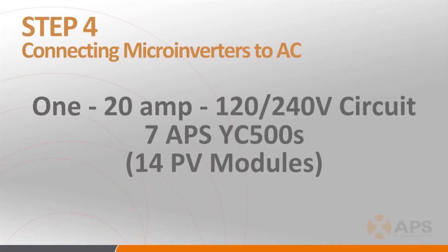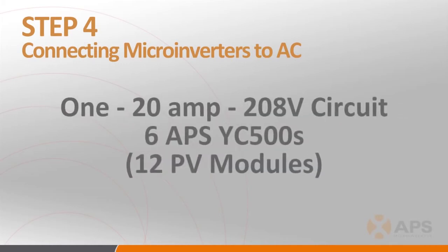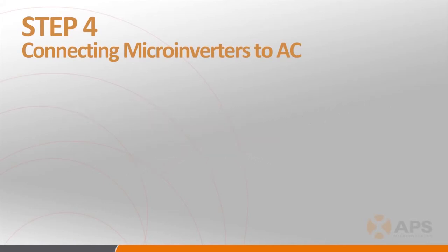When doing so, remember the branch inverter limits. The maximum number of units per 120/240 volt 20 amp circuit is 7, or a total of 14 PV modules, and the maximum number of units per 208 volt 20 amp circuit is 6, or a total of 12 PV modules.